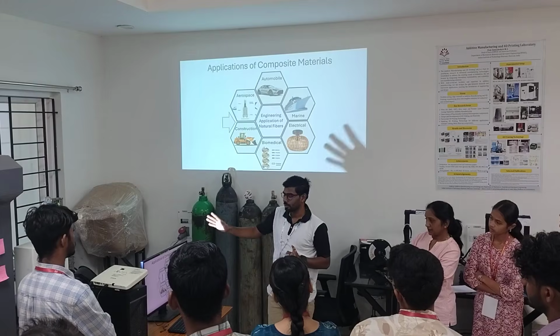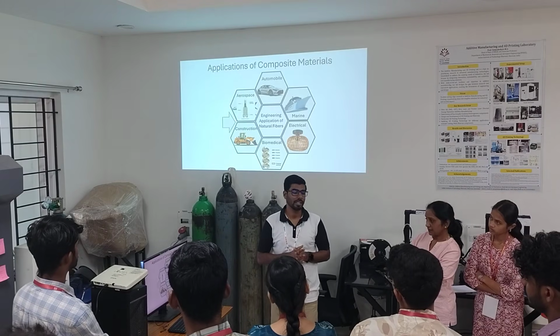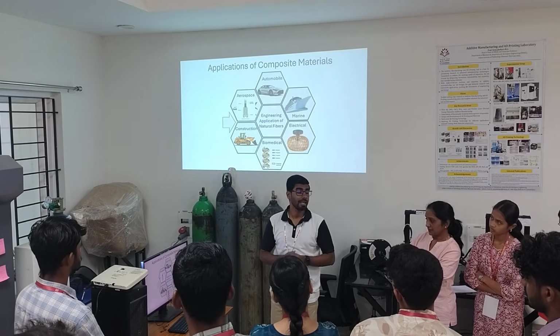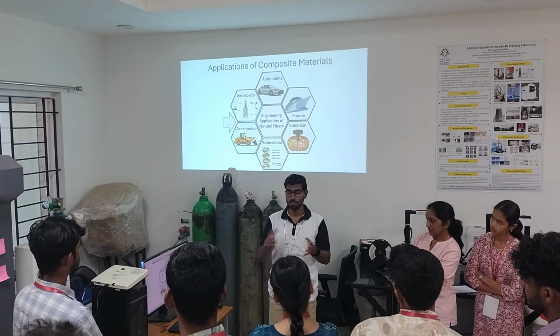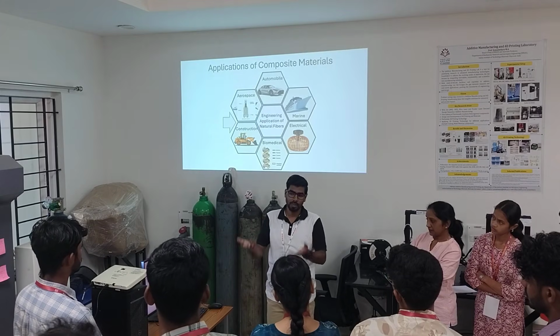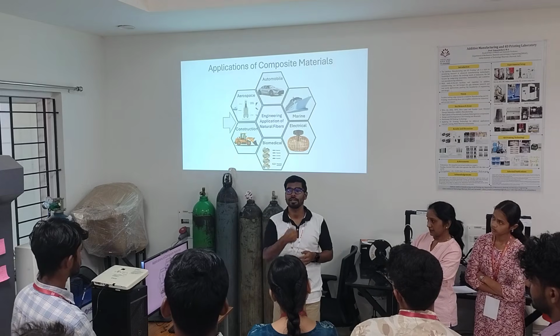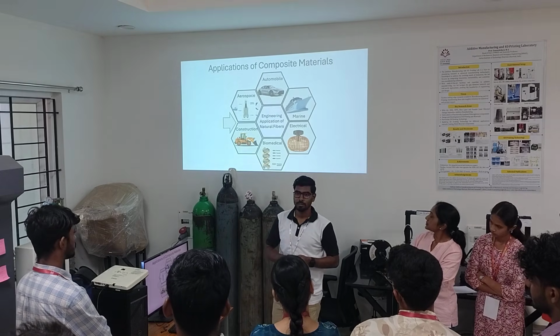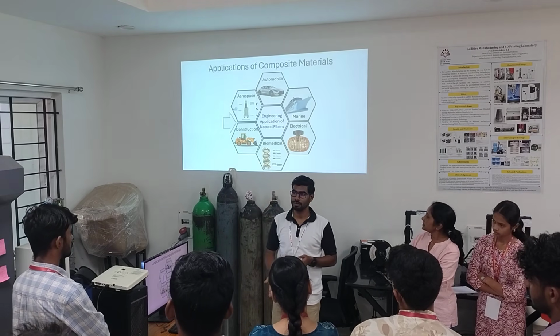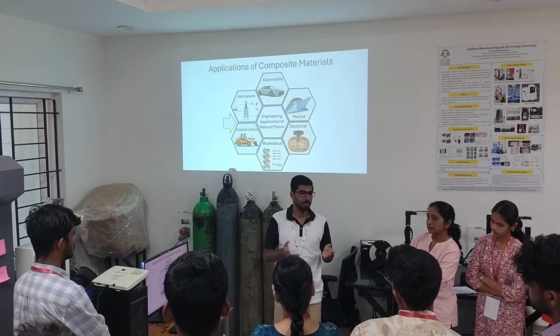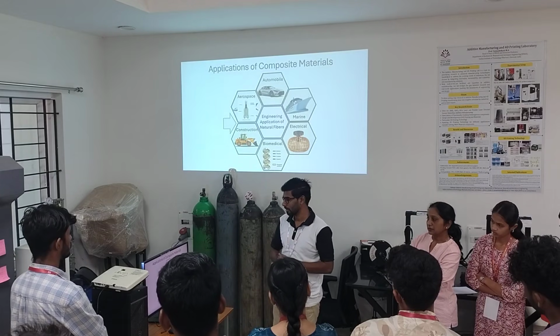Huge time goes into making those composite materials, basically done with the hand layup method. And that is, I should say, twice as safe compared to using panels and riveting them together, because there were lakhs of rivets. If any one of those fails, we have the risk of failure of the whole launch itself.